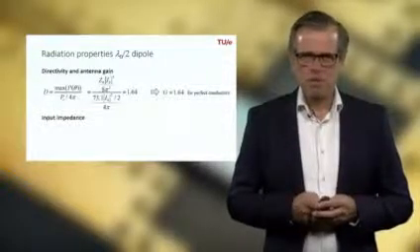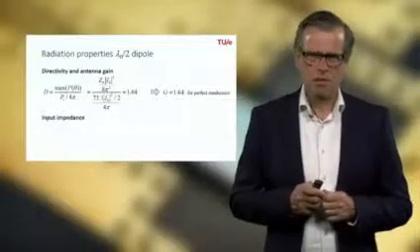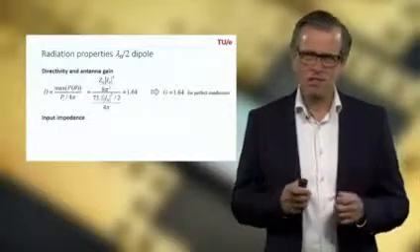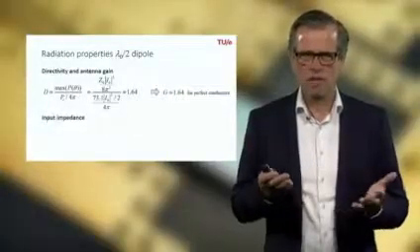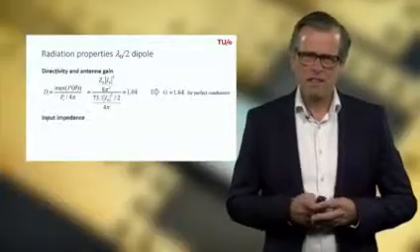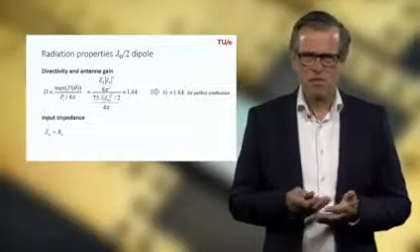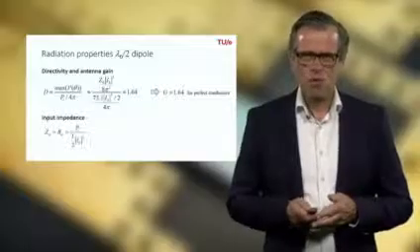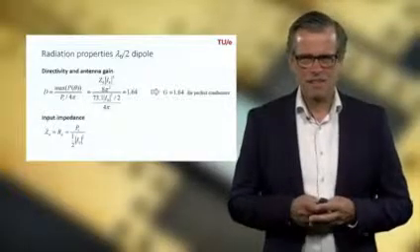The input impedance is very important, because that was the weak point of the electric dipole, as you can remember, where the radiation resistance was really low, much smaller than 1 ohm, so not very practical. In this case, you might already have recognized it. The radiation resistance, Ra, will be much more realistic.